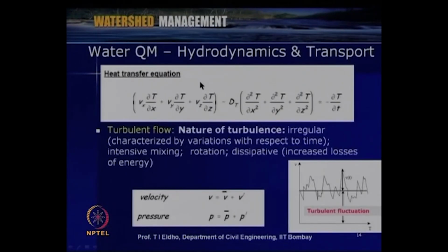So, then if you are trying to model the heat transfer problems, like we discussed, related to the heat transport processes which we have to consider, then the governing equation can be obtained like this, and this dt stands for thermal diffusivity coefficient and T is the temperature and Vx, Vy is the velocity variation. So, this heat transfer equation we can solve.